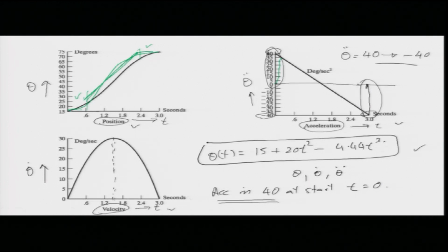Let me draw this again. Essentially we are saying that we are going to start very slowly like this, and end very slowly like that, which is going to be parabolic, and in between both of these we are going to connect by a straight line. So, this is starting slowly, ending slowly, and connecting the two by a straight line. This has 3 parts: one parabolic part here, one parabolic part here, and a linear part, and this kind of motion is called linear function with parabolic blends.